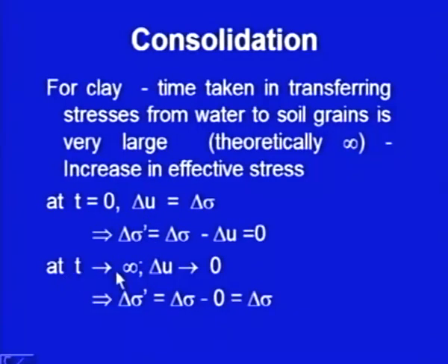As t approaches a very large value, the entire pore water pressure dissipates, it becomes almost 0, and then this term becomes 0, and delta sigma dash, that is the incremental effective stress, will be delta sigma minus 0, equal to delta sigma. So, effective stresses will be increasing to the extent of the applied surcharge stress.